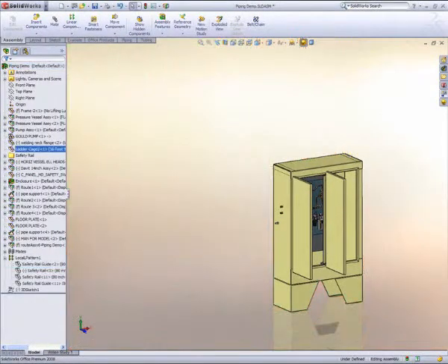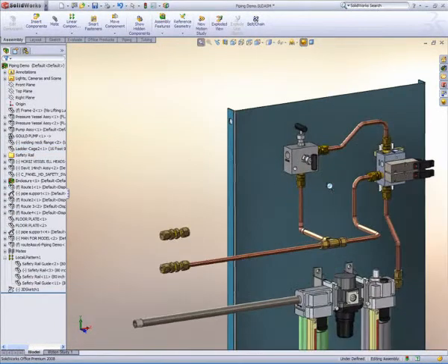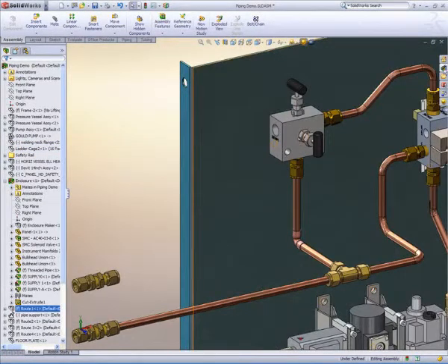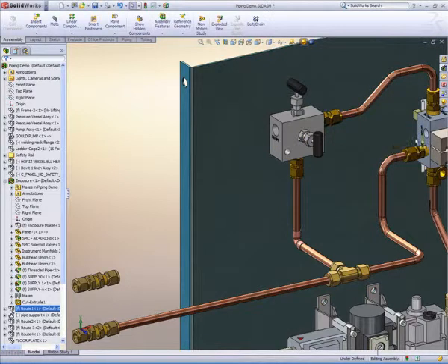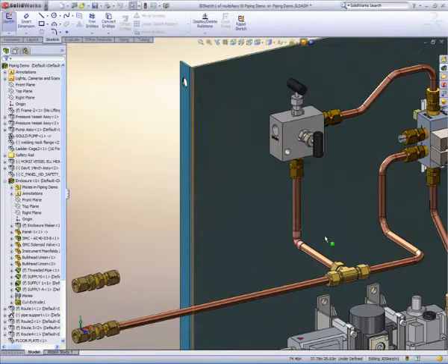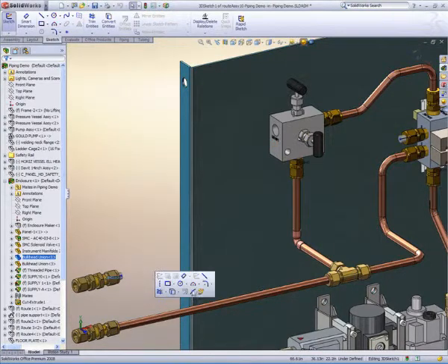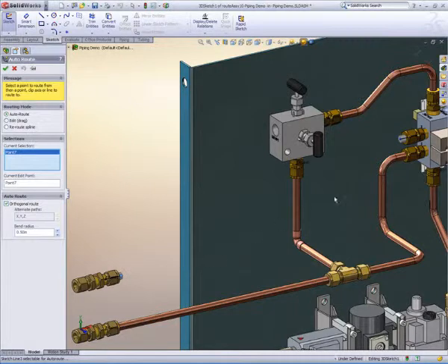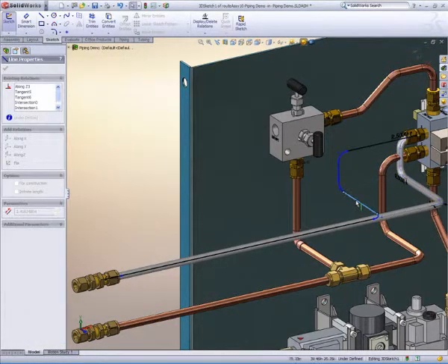Many designs not only incorporate piping for fluid handling, but tubing for pneumatic control devices. SOLIDWORKS empowers users to define tubing routes just as easily. Similar to how I defined pipe spools, I'm able to specify the beginning of a tubing run by utilizing SOLIDWORKS fitting libraries. Again, from the fitting, SOLIDWORKS has knowledge of tubing diameter and minimum bend radius. By specifying the destination of the run, SOLIDWORKS automatically routes the tubing.